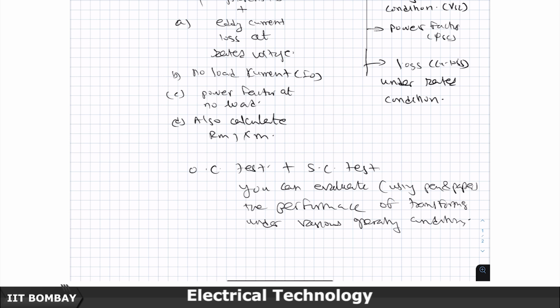So, every time you do not need to do tests, you do these two tests and done. Then you say half of the load transformer, what is the efficiency? Here I will give you the value. What is the voltage regulation? This is what I will do. Power factor has changed, I want to know how my transformer will perform. Here is my pen and paper calculation and the answers come out. So, that is the advantage of doing these tests and developing equivalent circuits.